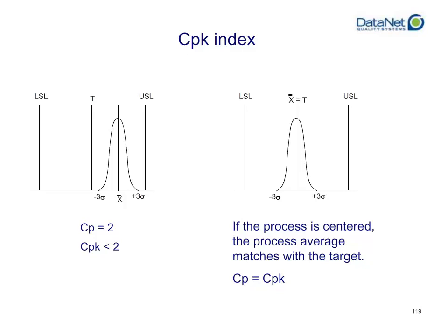If the process average matches with that target, if your CP equals your CPK, you are capable. You are as capable as you can be with that level of CP. So ideally, you want a very, very high CP value, and you want the CP value to equal CPK.